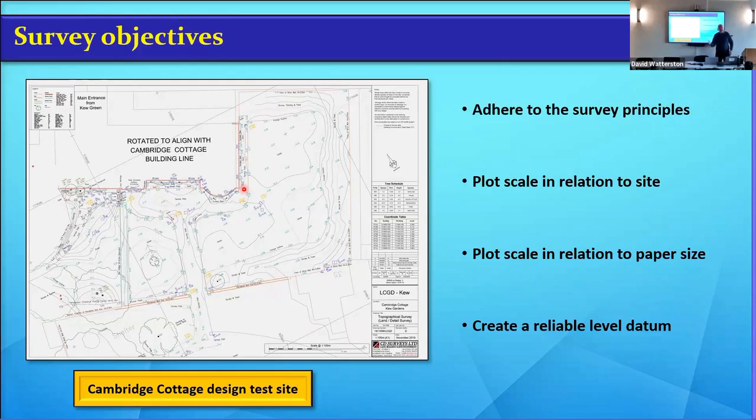Then you're going to end up with edge matching, or you're going to end up with overlap. And then it becomes not so manageable because you've got all these little bits. So therefore, you're better asking, can you give me this at 100 and give me these specific areas at 1 to 20, 1 to 50? And then ask the surveyor, if I want to come back to have another area, can you do that? And generally, they should say, yeah, for a small charge.